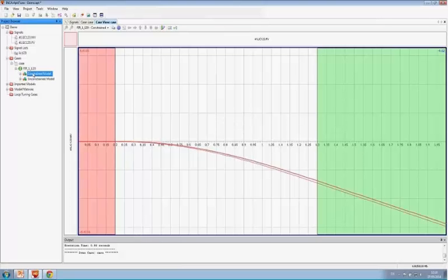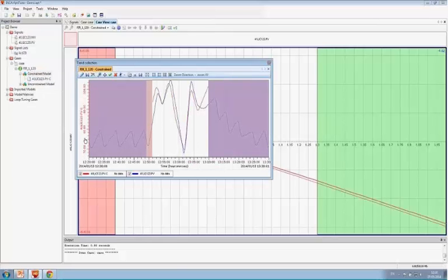So now, if I can judge if I'm happy with this model, I can go to that model and say show prediction. And now it's showing me the real data, as well as, let's say, the simulated signal for these steps. And the simulated signal is in red. As you can see, we have a reasonable fit. Some disturbances coming in here and changing and not fitting exactly, but all in all, a nice fit, I think.